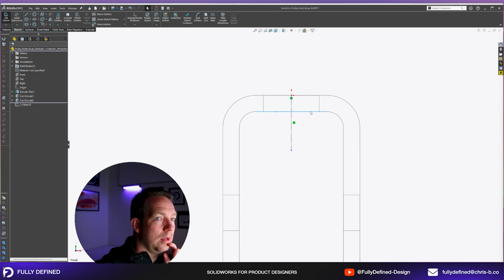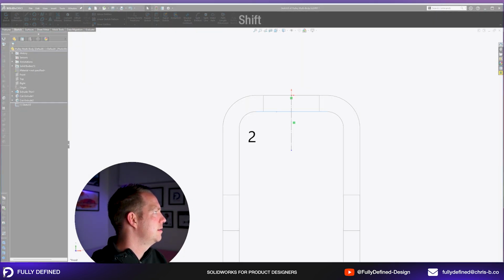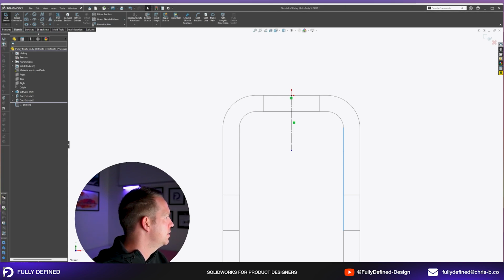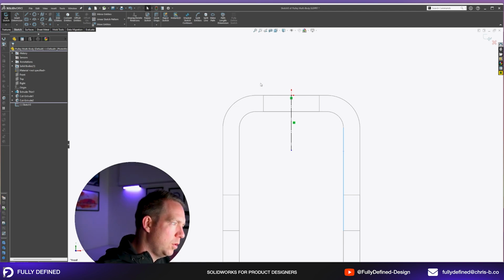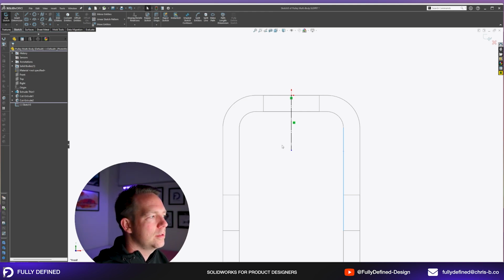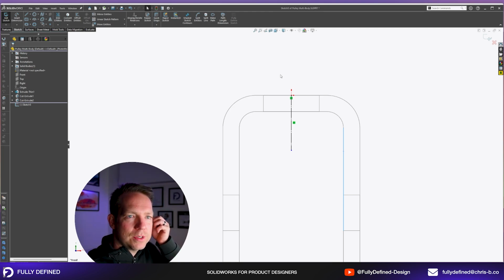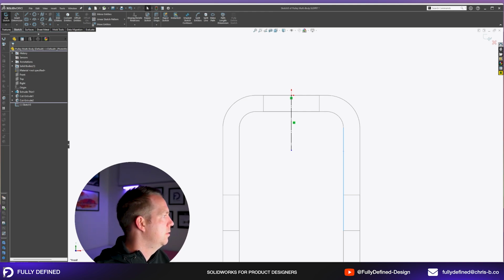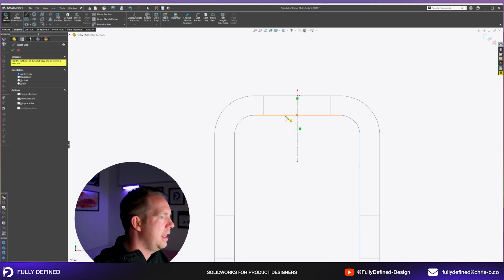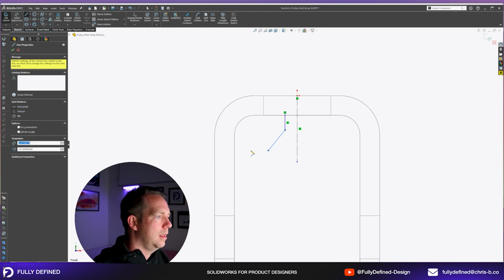We do that because that washer sits in that position. In our finished sub-assembly, the pivot pin that comes through, where the end of that has been pressed and formed, pushes back that washer up to that top surface. In reality, maybe it'll have a 0.1, 0.2 millimeter gap, maybe some lubrication, but for this project it's coincident with that face. So as I'm sketching, it's going to sit on that edge. I'm going to go coincident there, and then draw the rest of the shape as we've done in the past.